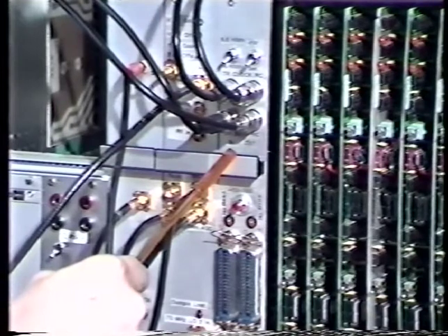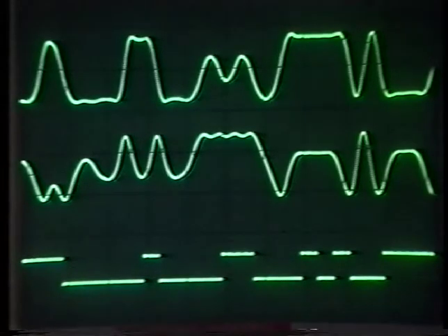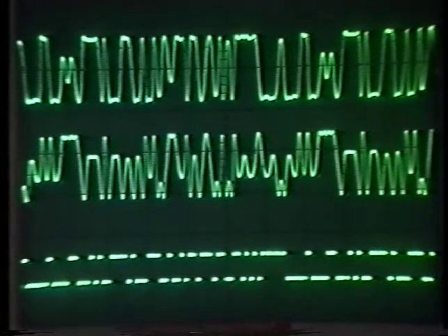The transmitter front panel is shown here. The sine and the cosine channels are the upper beams on the oscilloscope together with the input data. Less time resolution results in this figure. If the sine and the cosine are fed to an XY oscilloscope, this figure will appear if the bitrate is sufficiently low.